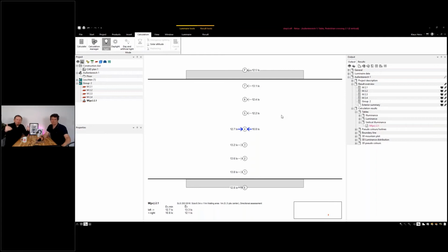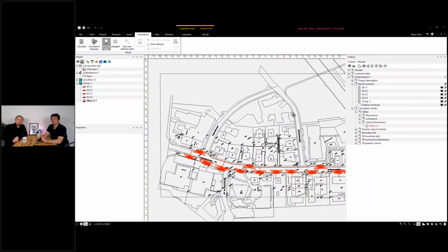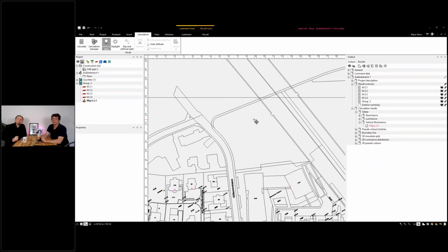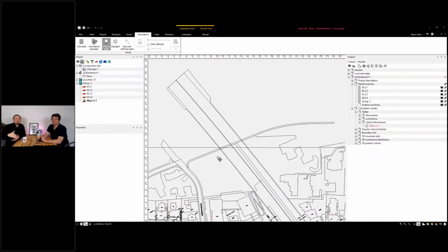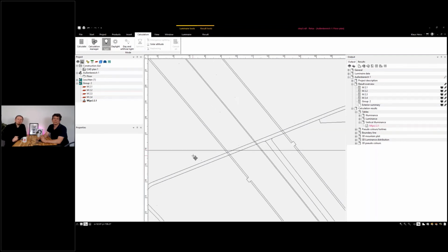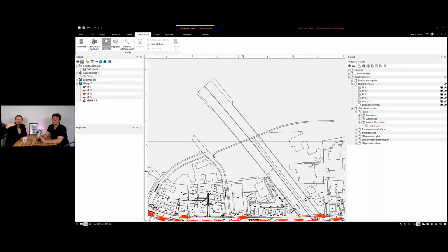You have an asymmetric light from two different directions, not to blind the traffic. But for the pedestrians, you have a higher illumination level on the crossing, and you need two asymmetric luminaires. And there are two German-speaking standards for how much the verticals on a certain grid should be.